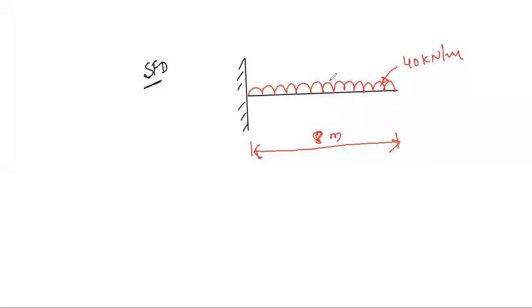See, for this, how to draw the shear force diagram now? Tell me. For the purpose of analysis, what we have done, we need to take some section over here. For example, if you take a section XX here, here a section YY, and if you want to draw the shear force diagram for this, let us make sections over here, right? Once you make the section, next we need to determine the shear force at each point. That's what we have calculated.